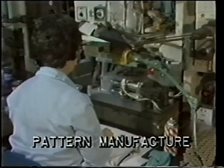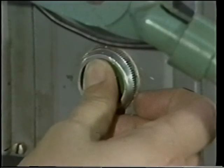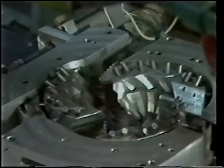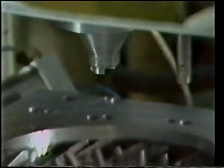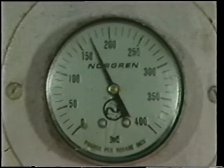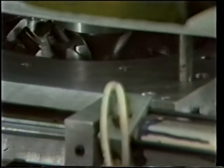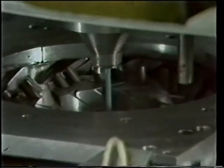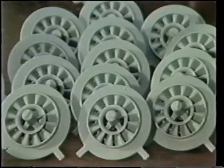Next, low-cost expendable wax patterns are produced. The master die is closed and heat-softened wax is injected into the die under pressure. When the pattern has hardened, the die is opened. The pattern is removed and excess wax cut off. An exact wax replica of the part is now available.